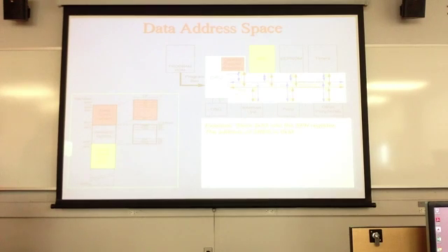And 53, all right, the address for the SRAM is 5F, so we're going to take 53, load it into R20, and then store that into 5F, which is the status register, which we will talk about today. So again, be careful picking your poison.